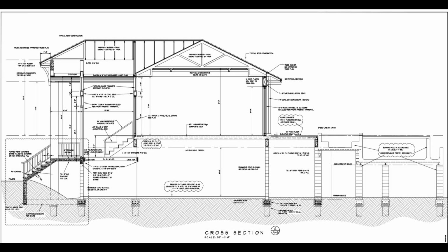There are also symbols that represent different wall details within the building. For example, this floor plan references wall detail B on sheet A7 and detail A on sheet A6. Notice the configuration of the arrow markers on these details. One is pointing up and the other to the left. The arrows represent which way you will be facing while looking at that detail. This is section A of sheet A6.